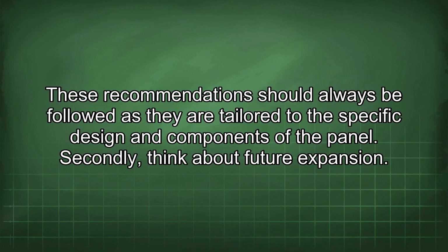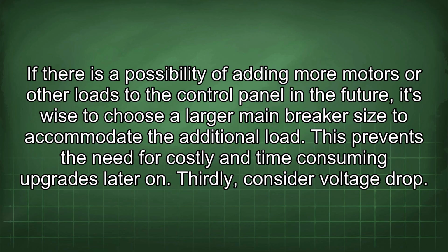Secondly, think about future expansion. If there is a possibility of adding more motors or other loads to the control panel in the future, it's wise to choose a larger main breaker size to accommodate the additional load. This prevents the need for costly and time-consuming upgrades later on.